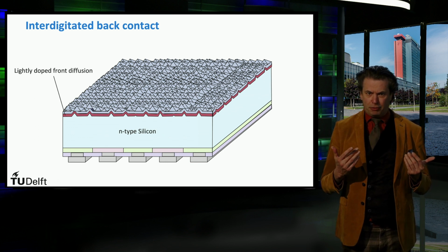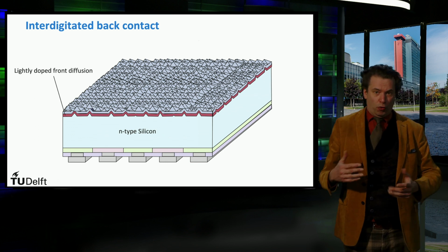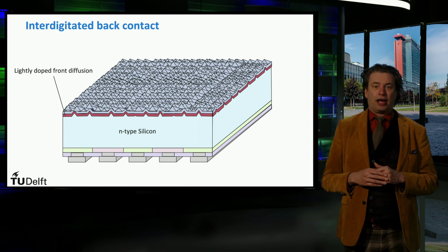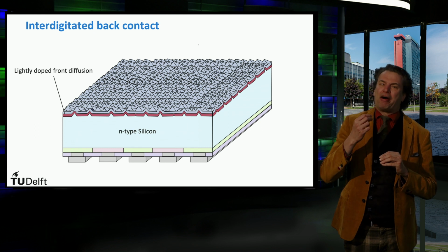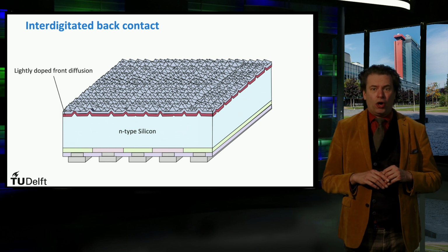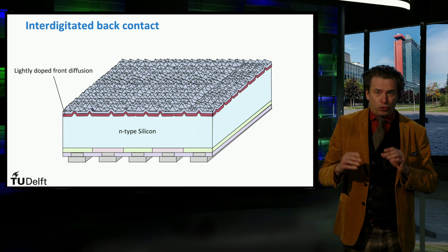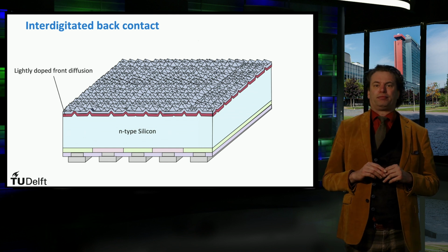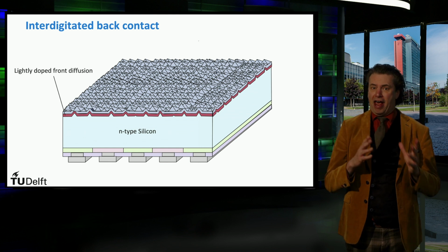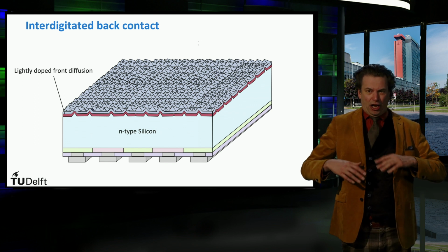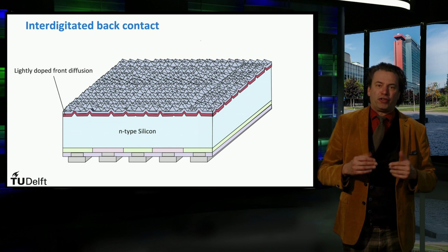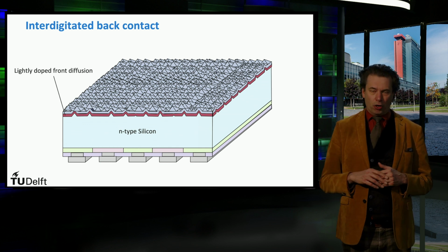The interface between the higher doped N region and the lower doped N region acts again like a PN junction. In this case, it will act as a barrier for the light-excited minority holes in the lower doped region to diffuse to the front surface. The front surface field behaves like a passivation of the defects at the front interface and allows to have higher levels for the hole minority densities in the bulk.